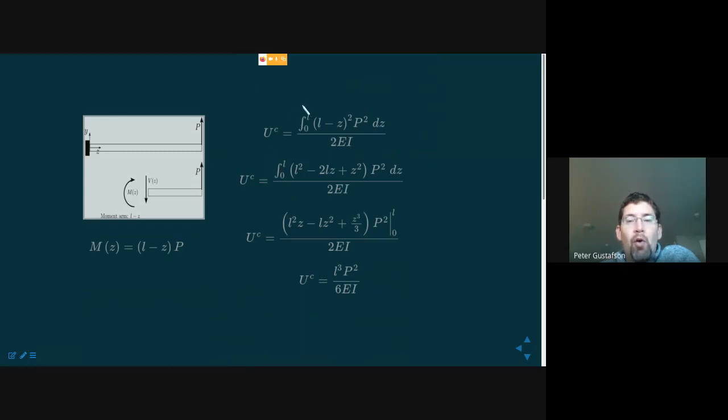Okay, so here I have now made a substitution. If I take a free body diagram, now we're looking at the bottom half of this diagram. If I take a free body cut somewhere in the structure, I know that I have still the point force at the tip. I have a reaction force, a resultant force really, at the boundary of my free body diagram. This is a shear value on the face, and of course I have a reaction moment there as well. Resultant moment really is what's better described as.